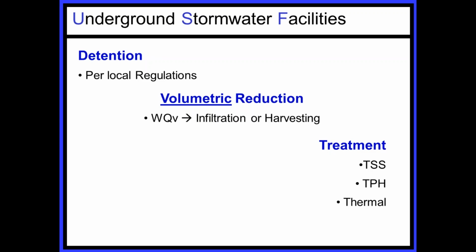So what we're going to be focusing on, and how to deal with these challenges, is using more traditional infrastructure, subsurface facilities for stormwater, and talking about 3 specific ways of doing that. One of them is detention, which is basically holding the water. Retention, which is basically permanently holding water until it's infiltrated. So in the retention environment, your design is set up to not allow any of that water to leave the site. And then there's also a combination of retention and detention in design.